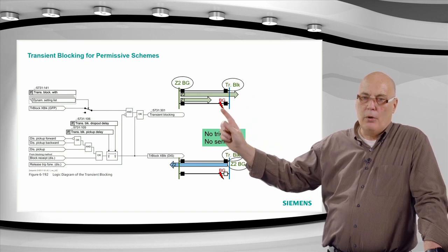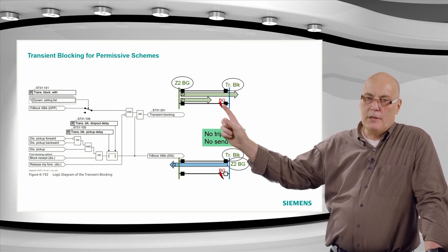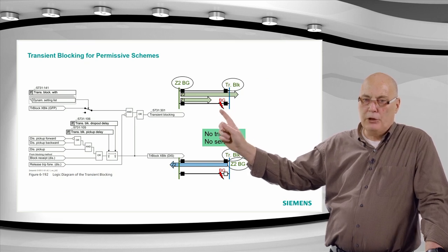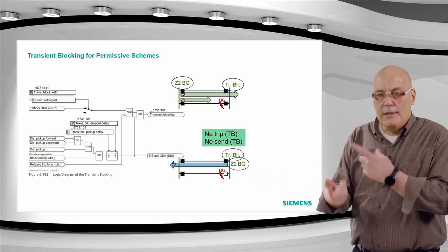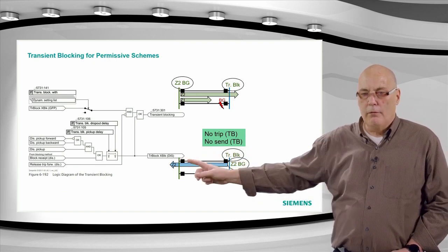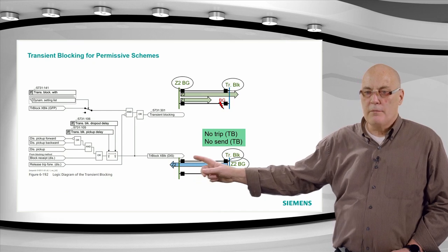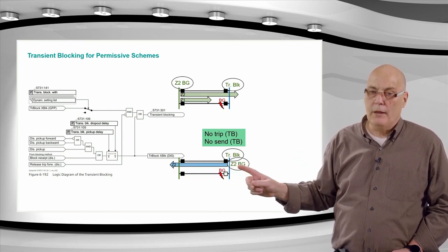And this side at the bottom we'll see the fault here outside zone 1 but inside zone 2, so maybe the teleprotection is not working so quickly, and then we go over to this condition trip, and now things reverse. So you get a reversal here, that now over here the zone 2 is going to reset, stop sending. Over here you could get a zone 2 pickup and send.